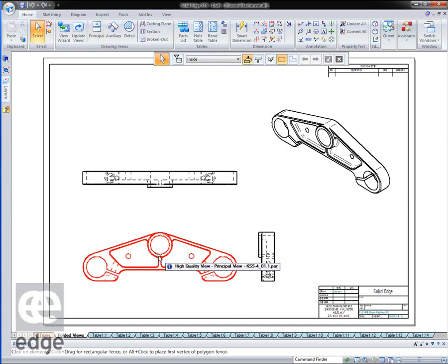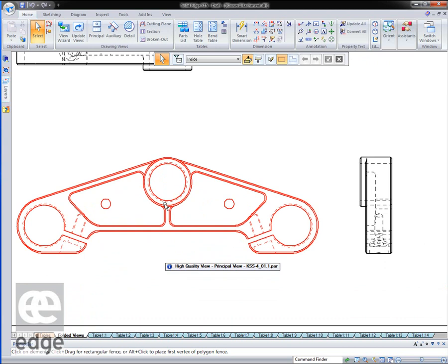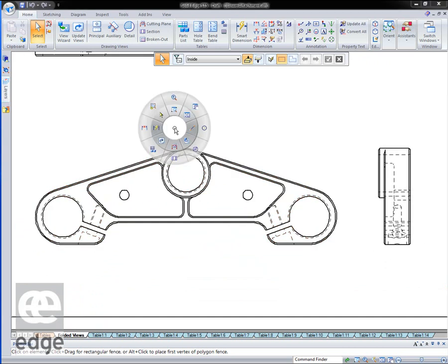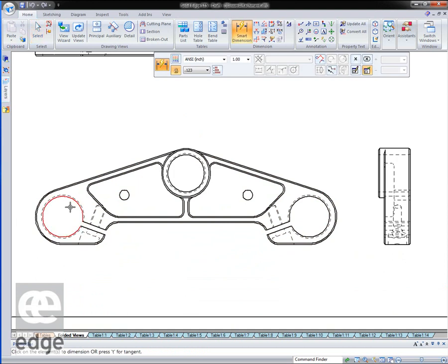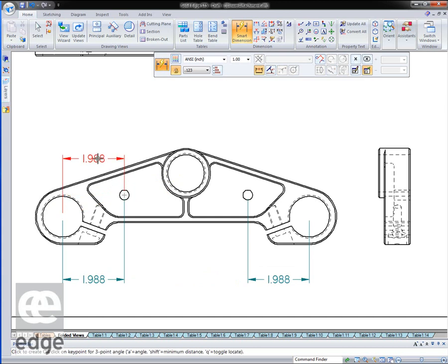But what I want to do here is to just zoom in a little bit, and we'll place some dimensions again. So using our distance between, pick up the center of there to the center of there, place a dimension. And again, I'm going to pick the center of that to the center of there, and I want to line those two dimensions up. So I just touch on this one, and you'll notice it snaps into place, and there's a little alignment line.